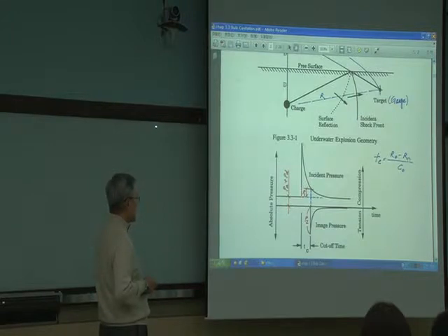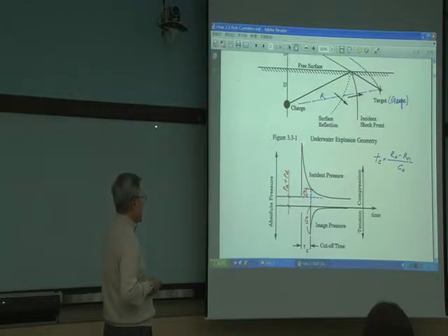Then here, from here to here, this is the shock wave pressure, P max. Then exponential decay, right? Then this is the time Tc. Tc is the time that the rarefaction wave hits the target. So this is max pressure for the tension wave. And you have to compute.